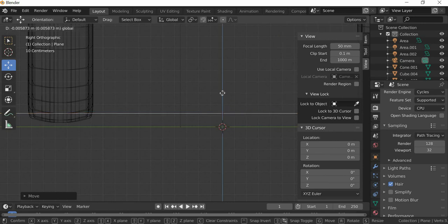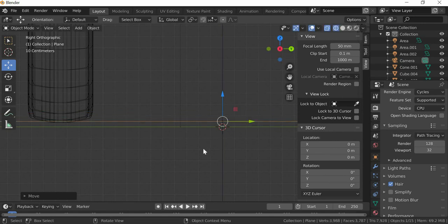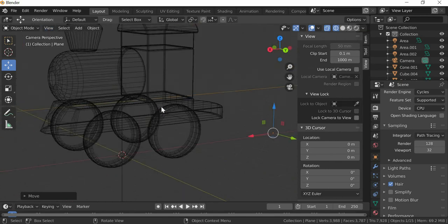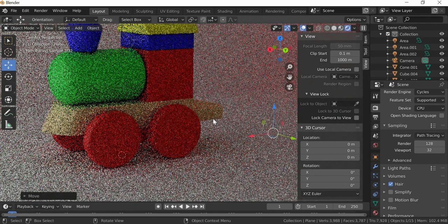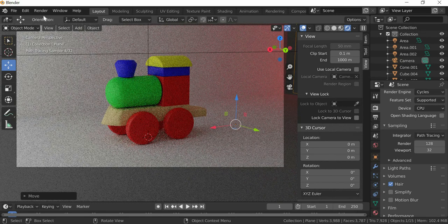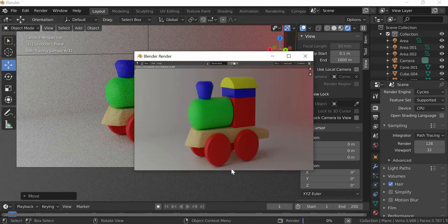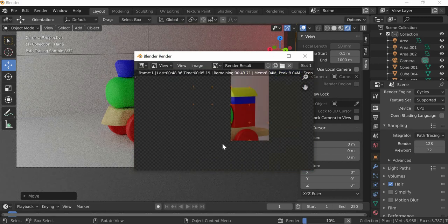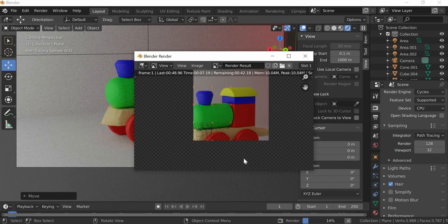And we look at wireframe and then arrange it. So that looks good. Okay, so you can go to view, viewpoint, camera, and then render it. So make sure that the wheels are on the ground. Okay, so this is important. You don't want the object floating in air.